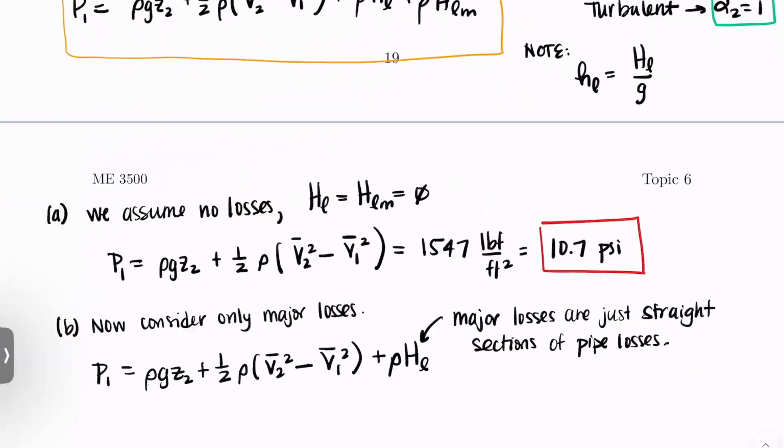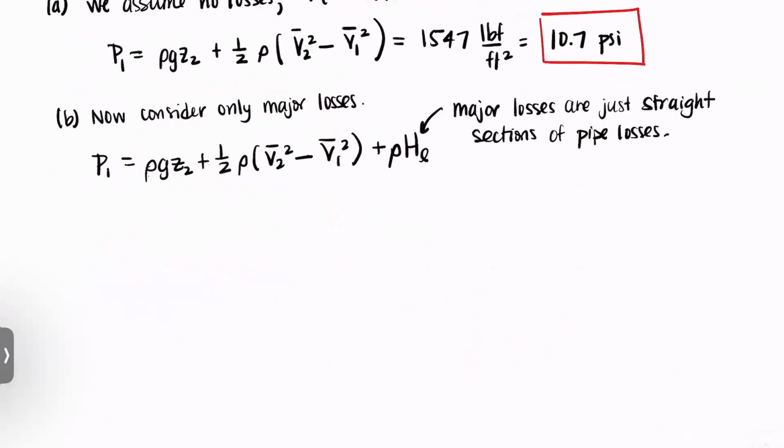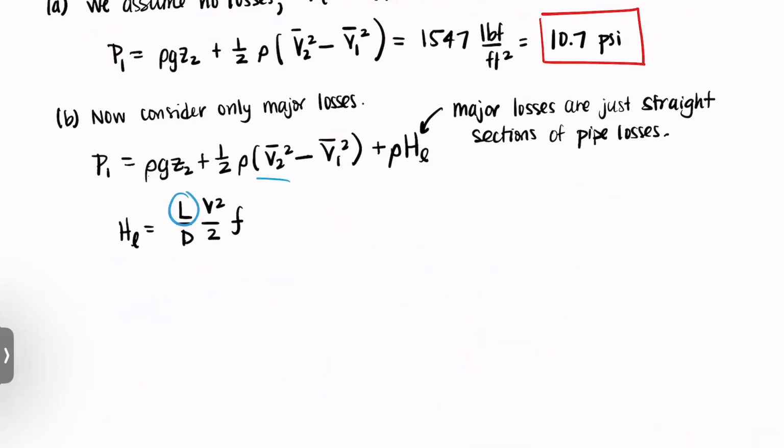He understood the assignment. Okay, so for HL, I'm going to write down our equation. So we have F times L over D times V squared over 2, as Owen already rapidly calculated. L is 60 feet of straight tubing.